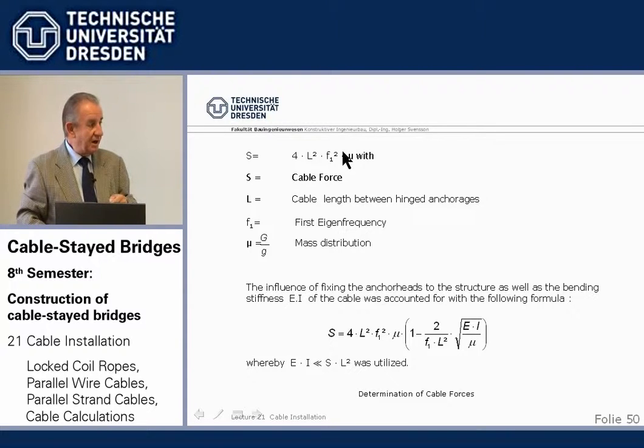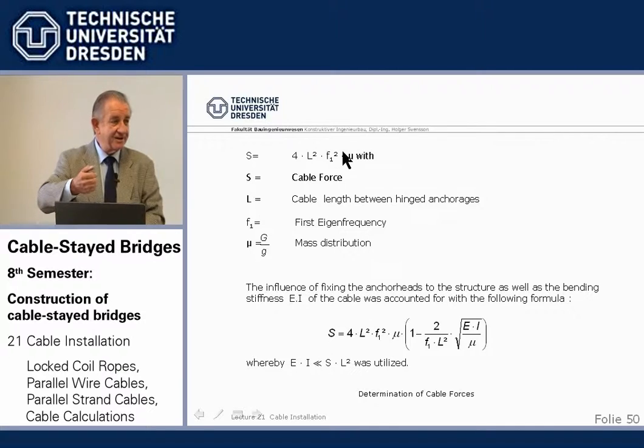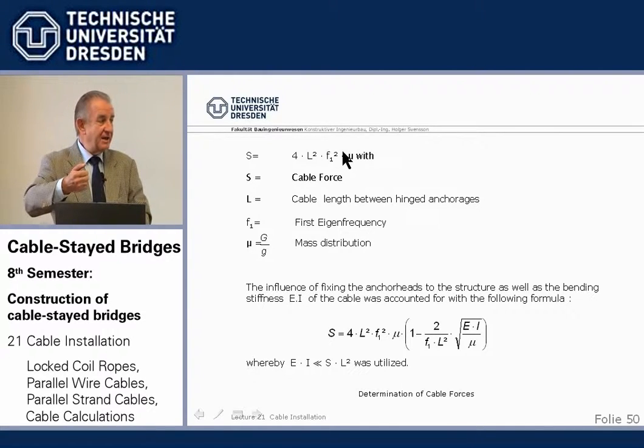You do it until it has something like that amplitude, and then you have a stopwatch and say, now. Then you count 1, 2, 3, 4, 5, 6, up to whatever you like. We've done it up to 100. And then you have the precise cable eigenfrequency, and from that you can calculate the actual cable force. That's the cheapest and simplest method, and it works beautifully.